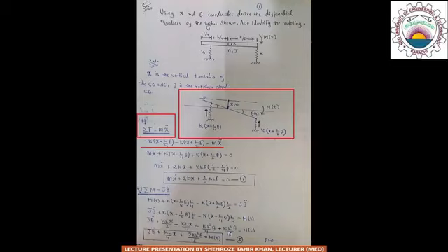and for this system, the arc length is given by L by 4 theta. So multiplying this arc length by the stiffness element, we get the force of our given system according to the corresponding stiffness elements. After applying the simplification procedure, the above equation becomes m x double dot plus 2kx plus 1 by 4 kL theta is equal to 0, and we may call this equation 1.